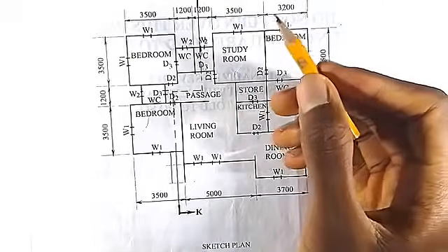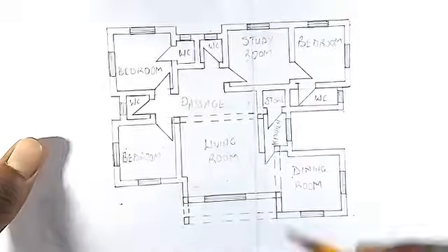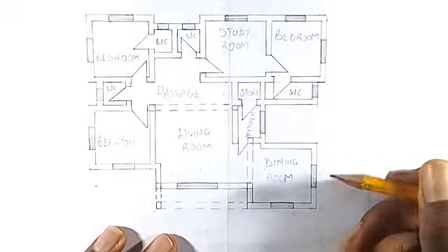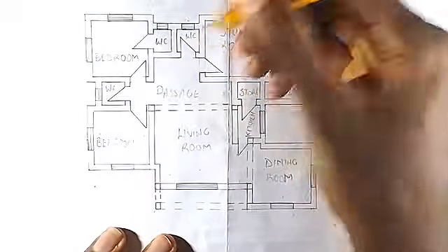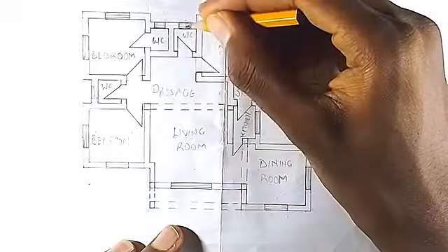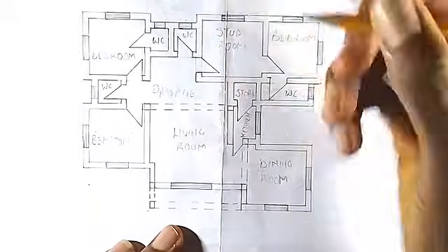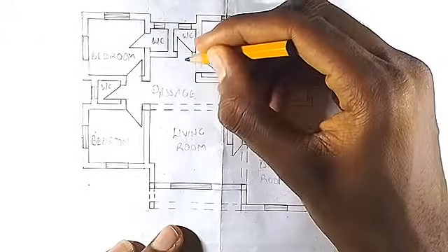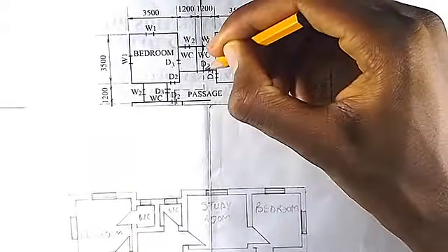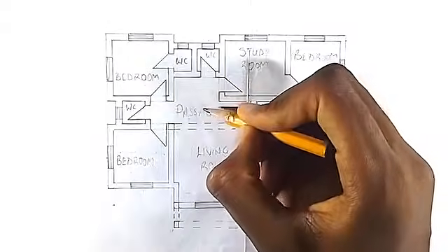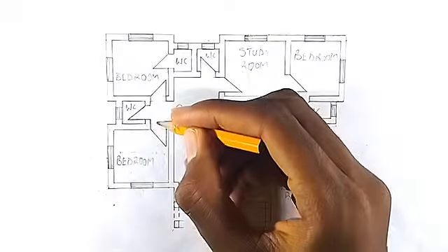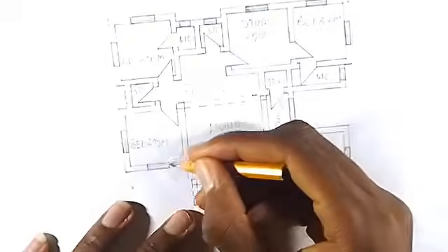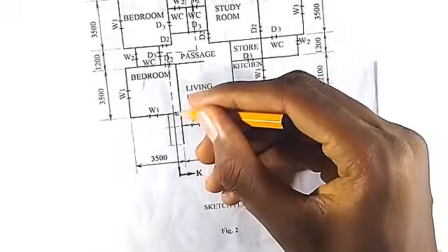So we'll just use our floor plan. This is the part we are using to section. We also section here, this window. We also have to section to this door, which is this and this. Then we also pass through the passage. Then we'll section to this door here, which is this. Then we'll section this wall, which is cutting to this.